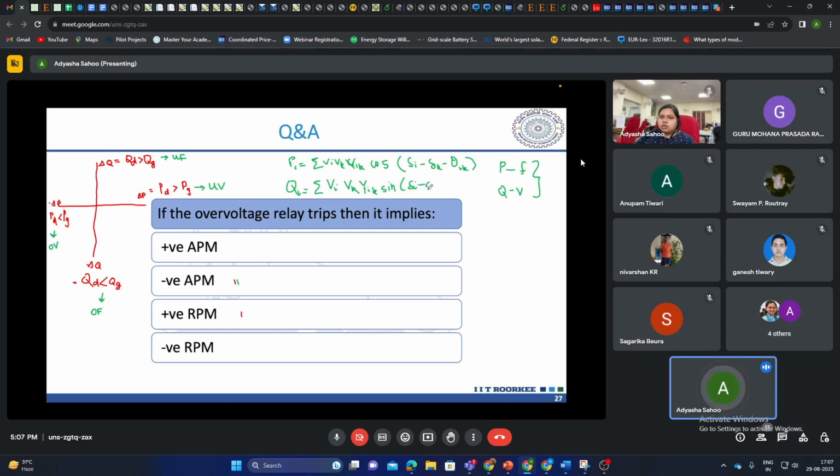So we can see that for the active power equation we have both voltage magnitude and angle, and in the reactive power equation also we have both magnitude and angle. But when we took some practical assumptions, we got this decoupling. Can anyone remember what those practical assumptions were?